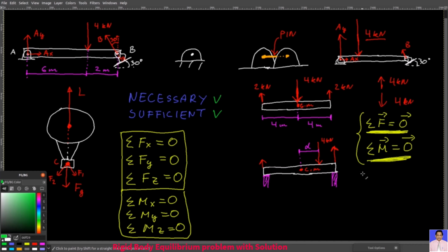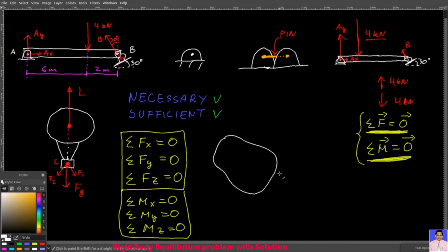And also, it does not matter what point I calculate moments about. For example, consider a random body. The sum of all the forces is your resultant force Fr. Let's say that it's 0 newtons. It's a zero vector. We apply it to point O. We also calculate all the moments about point O and then add them up. So we have a resultant moment vector about point O, and it's also a zero vector. So both the force and moment conditions are met. So the body is in equilibrium.